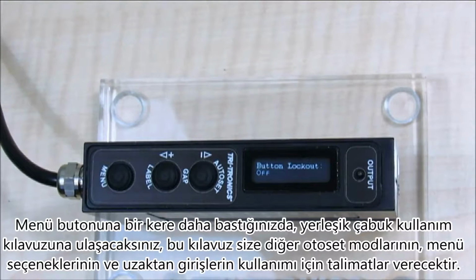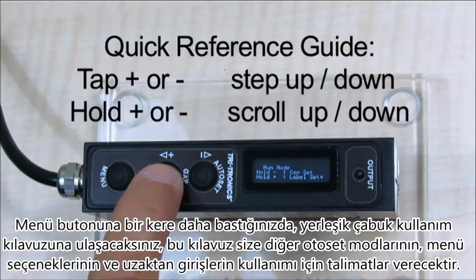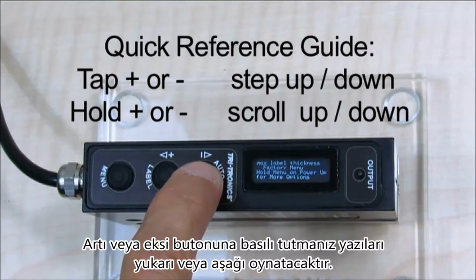Tapping the menu button one more time will bring you to the built-in Quick Reference Guide. This guide gives you quick instructions for using the auto set modes, menu options, and the remote inputs. Tapping or holding the plus or minus buttons will scroll the text up or down for viewing.